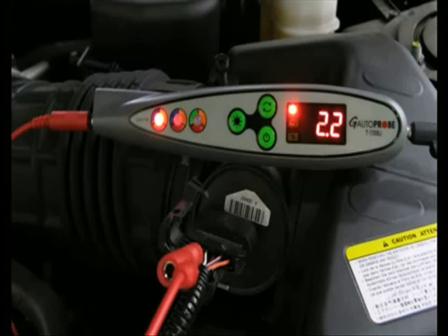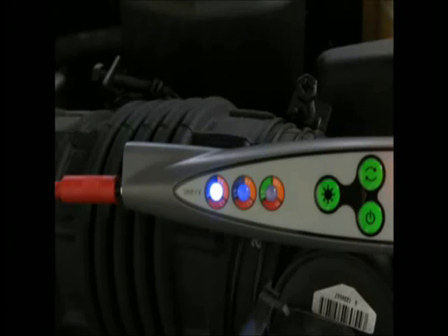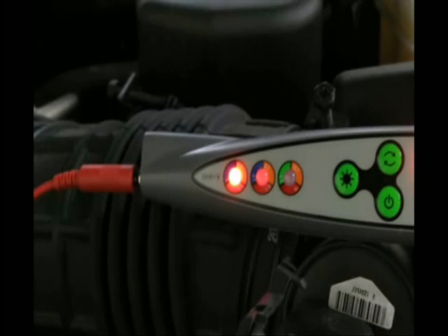It causes a serious problem when the electric ground condition is bad. The blue lamp at the bottom lights up if the ground is in good condition, between 0 and 0.5 volt. A serious problem could cause hunting on the engine. It means the ground of the sensor exceeds 1.2 volt, which is 10% of the whole voltage, and the red lamp at the first reflector lights up. You should start the engine, and all electrical instruments such as headlight, air conditioner, defogger, and audio should be loaded when testing.